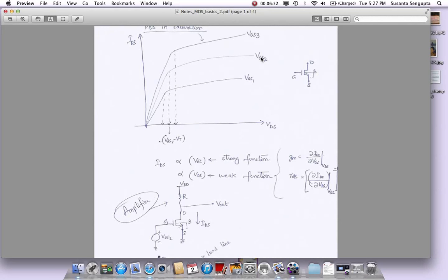So this 1 microvolt perturbation compared to 1 volt is a small signal. Let's say it was not 1 microvolt, it was 1 millivolt. It is still a small signal. It has a DC voltage of 1 volt, but for some reason I changed it to 1.001 volt, which is 1 millivolt more. I would still have another curve which will be very close to it. You won't be able to really tell much of a difference, and it will still be a small signal. There won't be much difference between that curve and this curve.